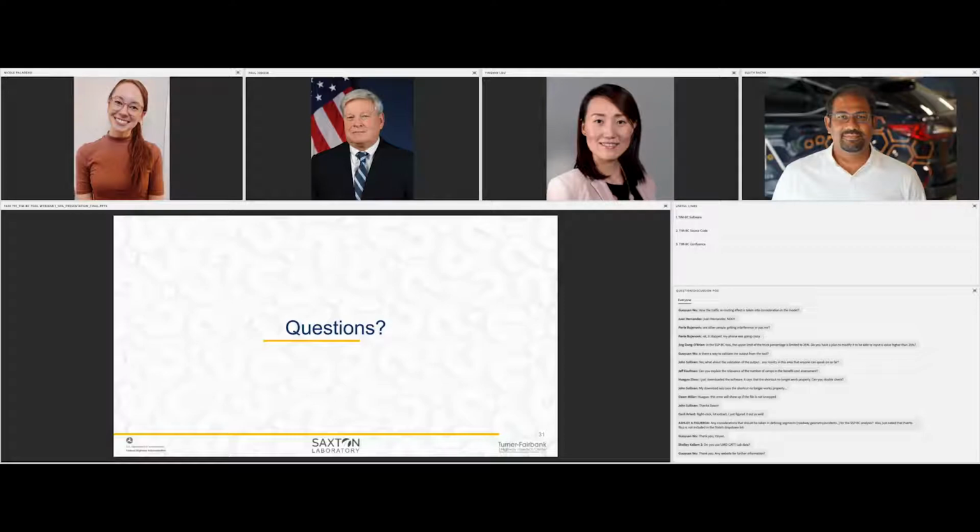Great. Next question. Can you explain the relevance of the number of ramps in the benefit cost assessment? Yes. Thank you for the question. I believe the roadway geometry, including number of ramps, terrain, and horizontal curves, are taken into consideration in the analysis tool by adjusting the free flow speed. So all of these factors will have an effect on the actual speed of the traffic. And the speed of the traffic is actually a variable in the calculation of the total travel delay. It's in the regression equation as an input variable. So the number of ramps, the terrain, and the curvature are all taken into consideration through the speed.